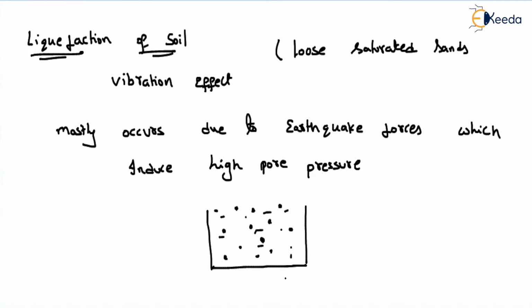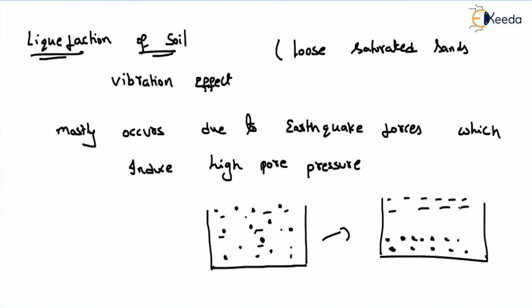Suppose an earthquake happens here. Because of the vibration, what happens? The soil particles come close to each other. As they come close to each other, the volume will not change. But what is happening? If I keep my piezometer here, my pore water pressure is increasing.